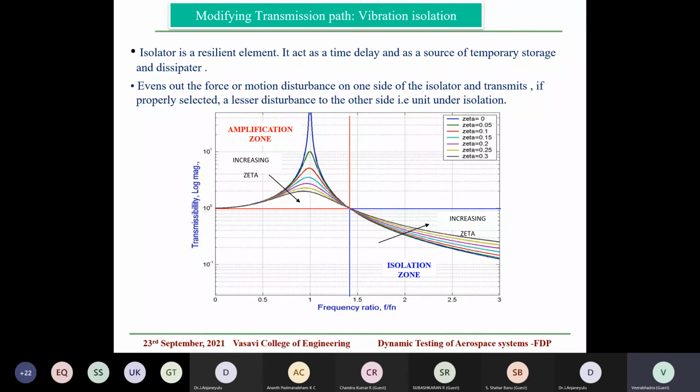But if it varies by more than 1 or 2 hertz, say one isolator is 20 hertz, another 22 hertz, another 26 hertz, then your system may isolate in one axis, but in the cross axis you will see more motion than required.